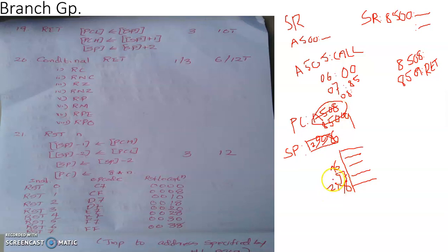And the content of the stack pointer plus 1 memory location: the stack pointer content is now 2996, so stack pointer plus 1 is location 2997. The content of this memory location is A5. That will be taken back to the program counter. Then 2996 and 2997 are empty. The stack pointer needs to be updated to the new stack top, the address of the maximum filled stack location, which happens to be 2998.